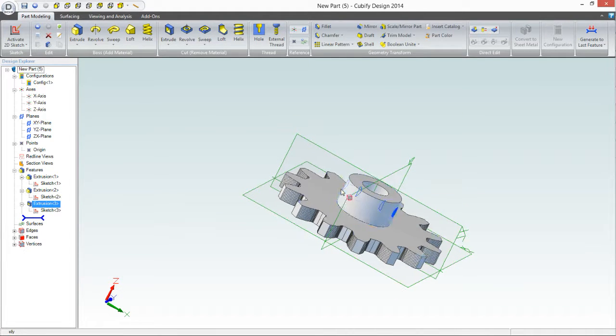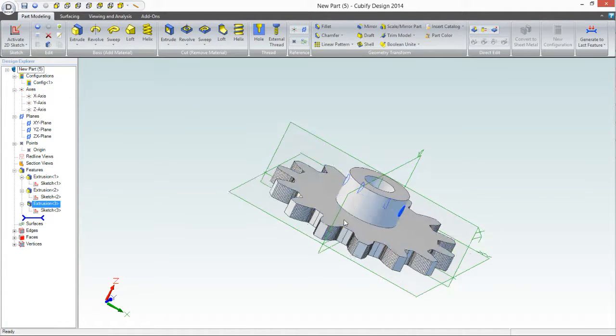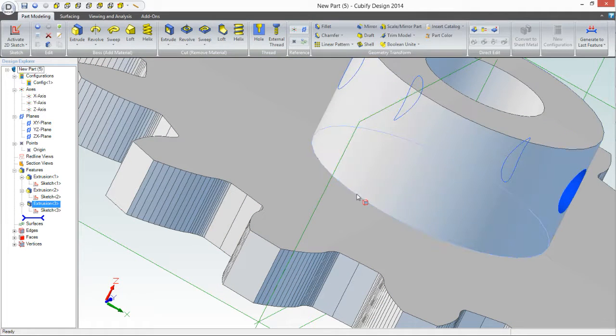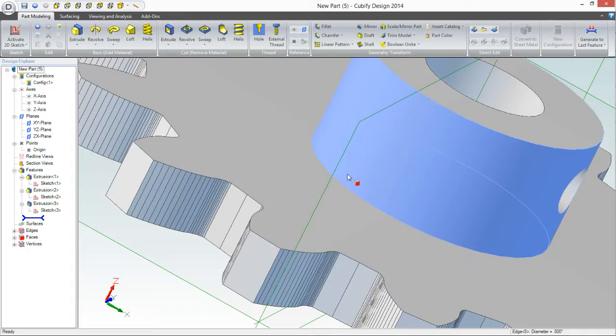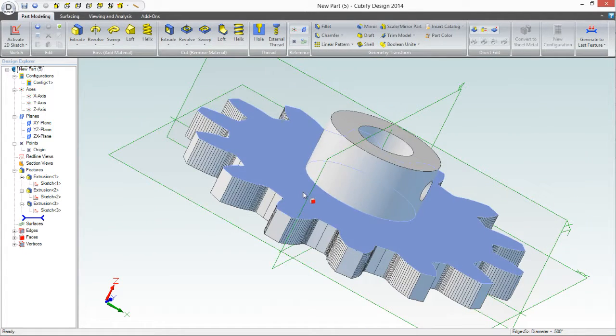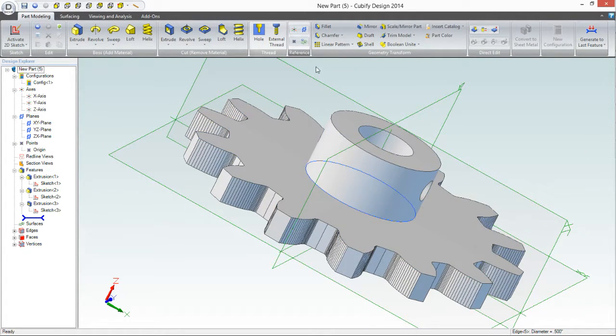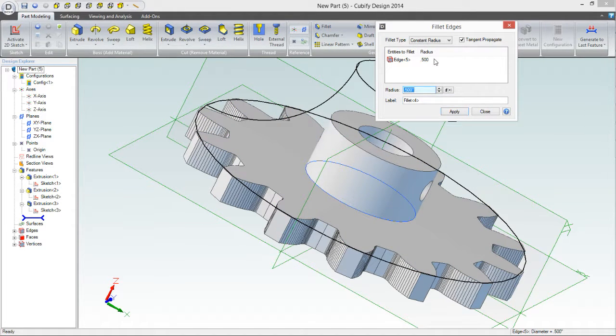Hubs are always stronger if you get rid of this little spot right there. You've got to get that little 90-degree section filleted. And so what we're going to do is use fillet. And you see fillet, remember it always starts up with a 1/2 inch fillet. Now we don't need anything that dramatic.